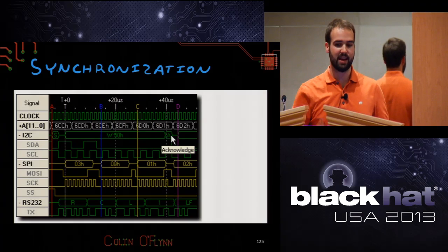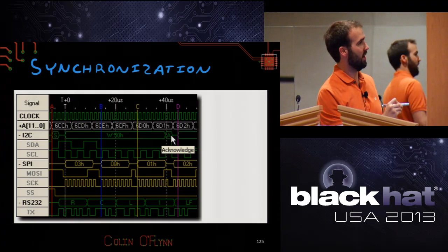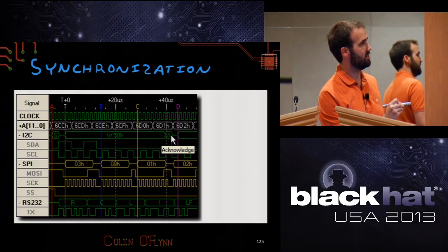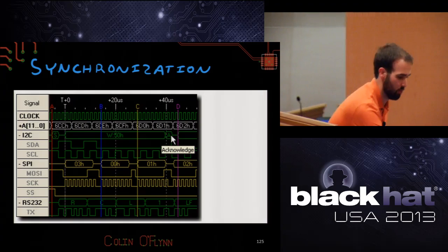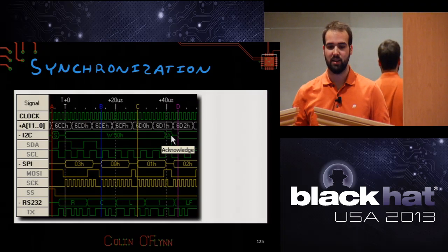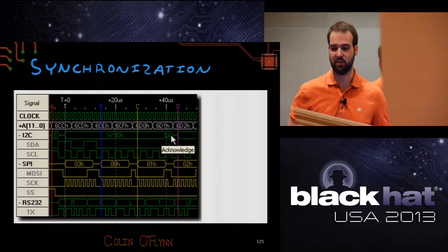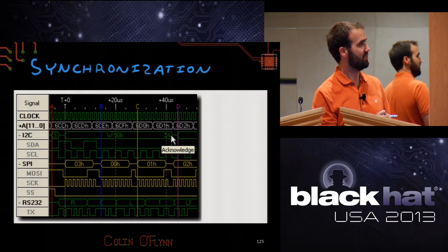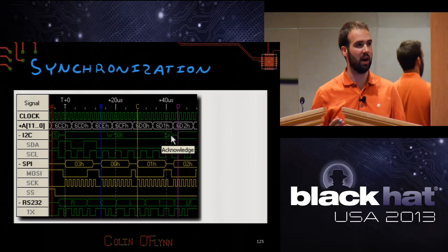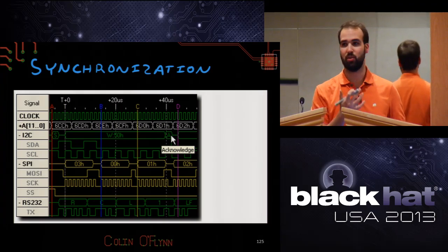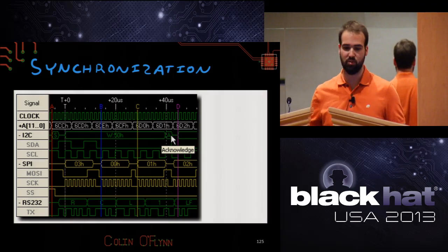What you need to do instead is to monitor the IO lines of the device, for example, and say, well, I know when I send it some byte, which is some binary pattern, then it's going to run the encryption, or maybe then it runs it after so many clock cycles. So there actually is support for this in the ChipWhisperer hardware. It's only loosely tested, which is to say you can say, wait until some bit pattern occurs, wait until I send the encryption command or the guy sends back okay, and at that stage, do the recording.